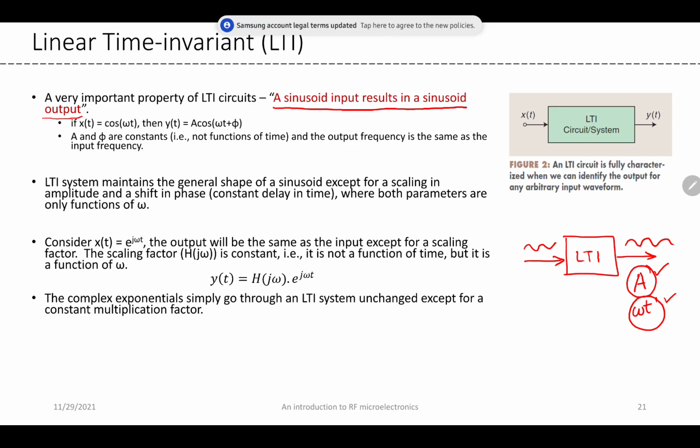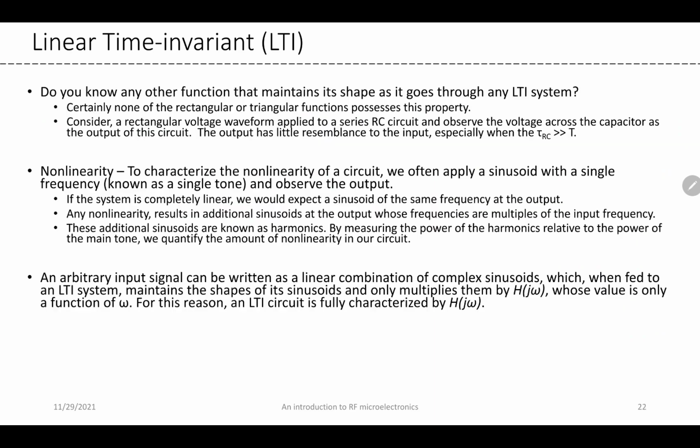And as I mentioned, they maintain the general shape of a sinusoid except for a scaling in the amplitude and a shift in the phase. So these are the only two things an LTI system would do to a sinusoidal input. And that's all for LTI systems.